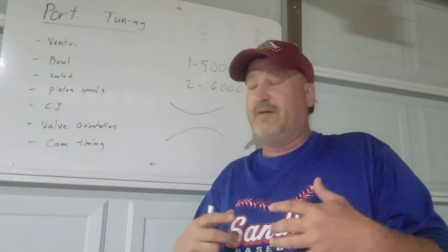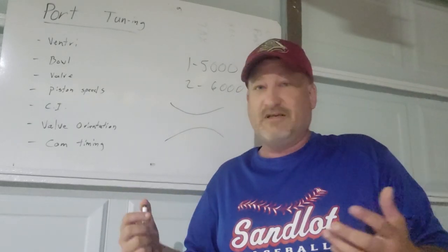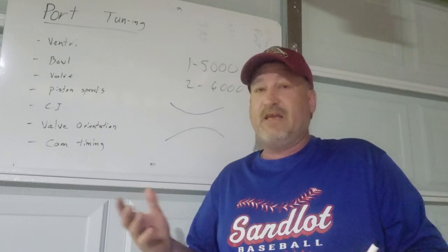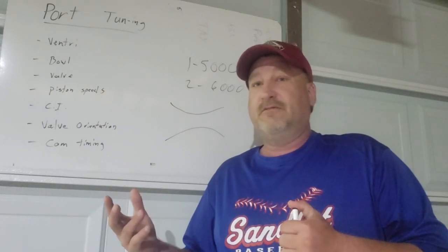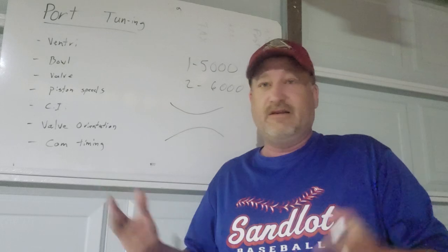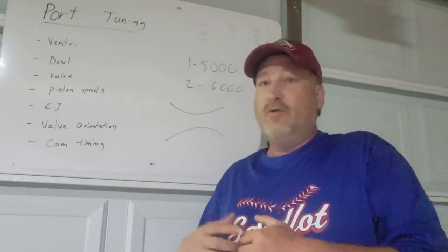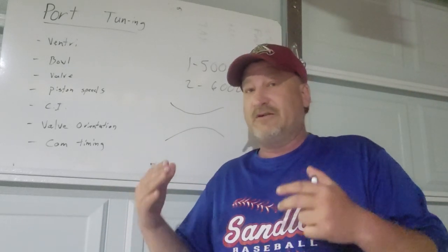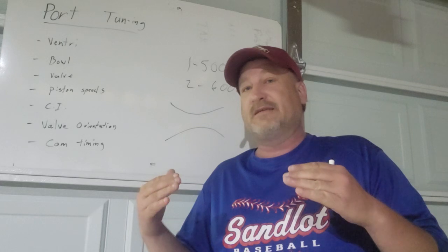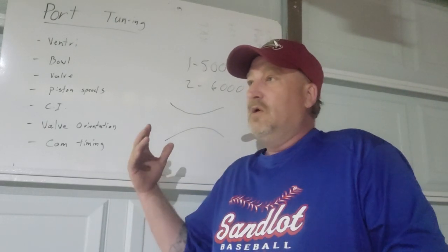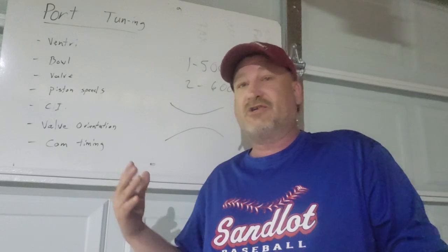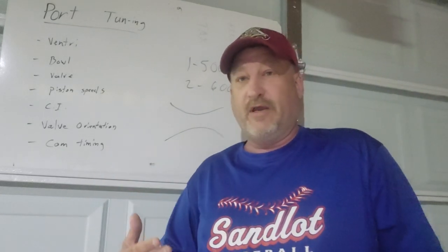Okay, even with the most advanced exhaust systems out there that can evacuate the previous ignition sources and flame front, they don't get rid of everything. So there is a negative pressure within the cylinder when the valve is initially opening up. But it's the ram effect that actually gets the movement going.